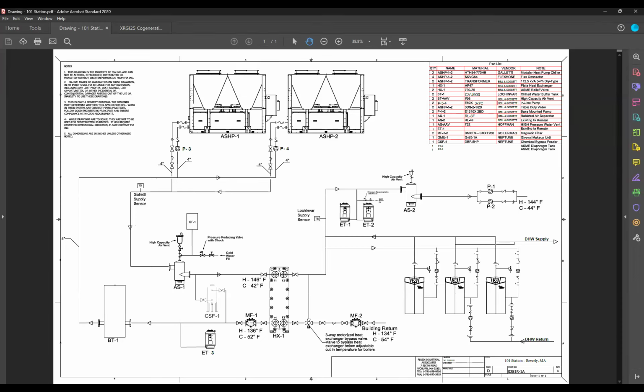A couple benefits of hybrid systems is that as your ambient decreases and your output decreases, we only have to size it to whatever that switchover is going to be. So if you say, my point of diminishing returns for my incentive dollar is around 20 degrees for the most part, at 20 degrees my heat loss in the building is X. I can buy a heat pump that derates to X, rather than having to buy an even larger heat pump that covers you down to 10 degrees when maybe you don't get incentive dollars beyond that, and your operating costs are higher. So it really depends on the scenario, how clean the grid is, and what your customers' goals are.